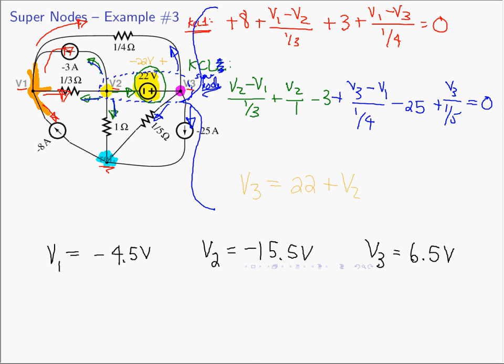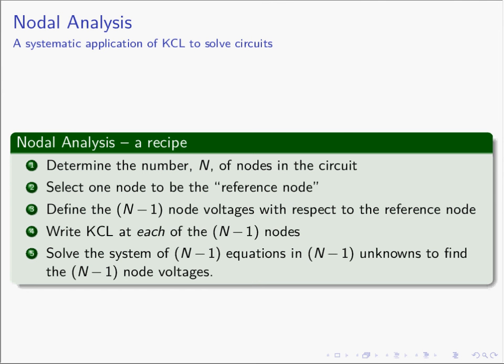So here we've seen that when our nodal analysis involves voltage sources, you're going to have a supernode. The reason that comes up is because we don't know the current flowing through a voltage source, and remember, nodal analysis is an application of KCL. If we don't know the currents flowing through a voltage source, then we have to do something else. So we combine 2 nodes to make a supernode, and then the voltage source itself gives rise to the equation to make up for the fact that we've lost one.